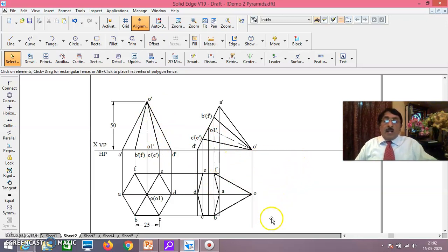For this, what I've done is, first step is I completed the outer boundary. And then the second step, when you're looking from the top, base is nearer than the apex. That is, base is seen by the observer. I have darkened the base. Now count the number of edges. 6 plus 2, 8 edges are over. You're still left with 4 more edges.